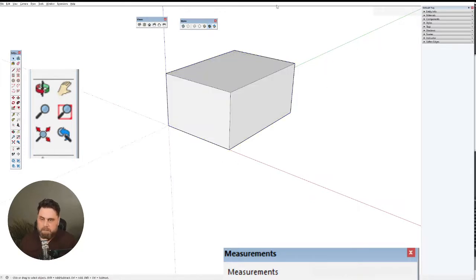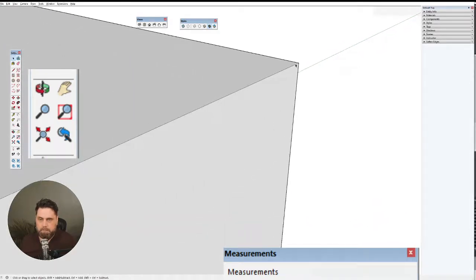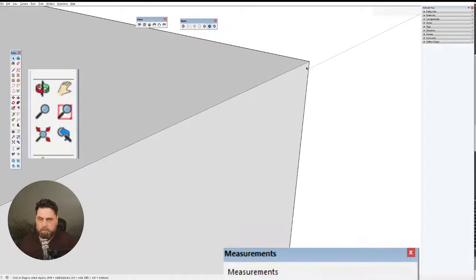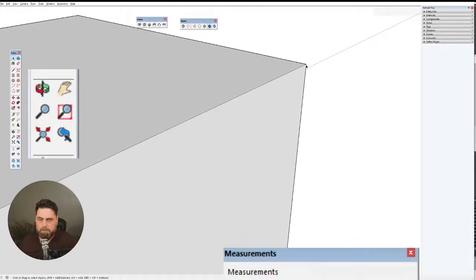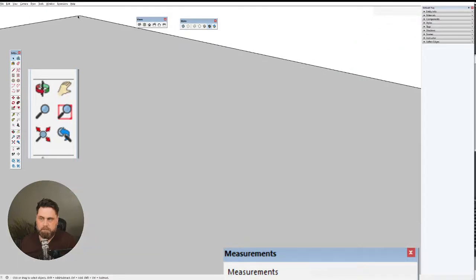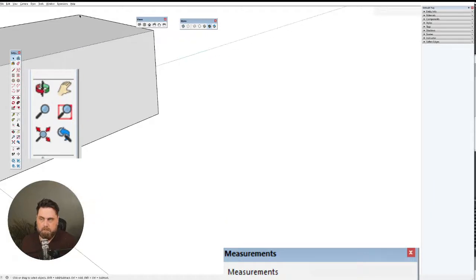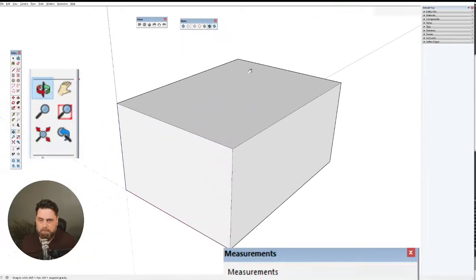So we're in the select tool, and let's put the select tool up into, let's say, this corner. See, when I scroll in, I'm going right to that corner. So even if I go up here now, it's going to scroll me in over there. It's not going to center it, but it's going to scroll over where I am. So for me to center it, middle mouse, shift, pull it down.